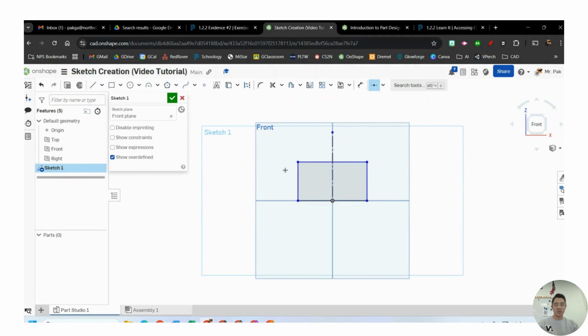So let's go ahead and keep things cruising here. I'll start off by making this shape. Again, I can use this as a reference, drag it out, and finish up that top portion. And make sure that this is the midpoint of this line. And then the 3-point arc is over here. Click on this point, drag this out. And I do want that middle.